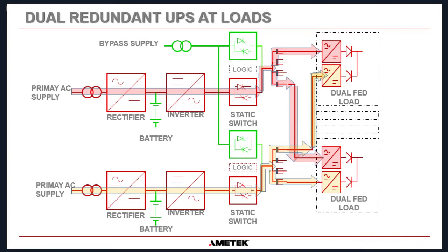I've seen dual, I've seen triple inputs to DCS systems. And what that allows us to do is remove the complex circuitry that allows the 2 UPSs to synchronize together. Okay, and basically what we're doing is we have 2 standalone UPSs.